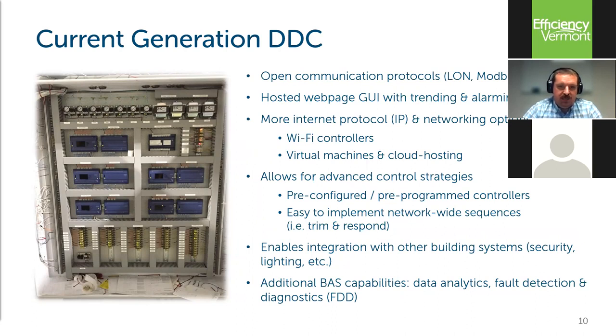With these open communication protocols too, it became easier to build out our networks. We required less and less gateway devices. A lot of the time, we even have the ability to go straight from a terminal controller like a VAV and go right up to a server with no supervisory controllers or gateway devices needed, because it's all IP based now. Our programming tools and our devices now become much more universal.